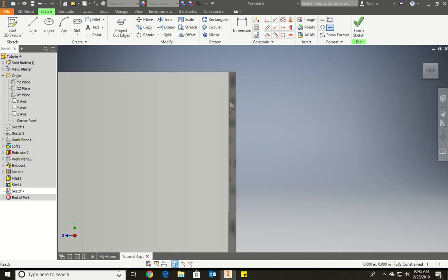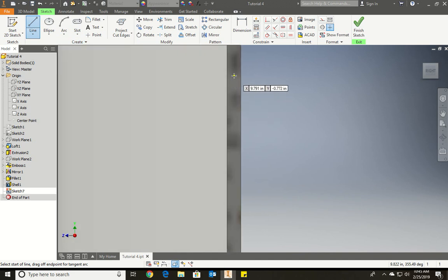Again, we're going to use dimensions to fix it, but just in case, we're going to draw halfway in the middle, like so, the shape of the tooth. So like this, we could draw what, guys? We'll draw a line here. We could draw another line here. And we'll draw an arc afterwards. So we have something like this. Okay? So we have this nice profile.